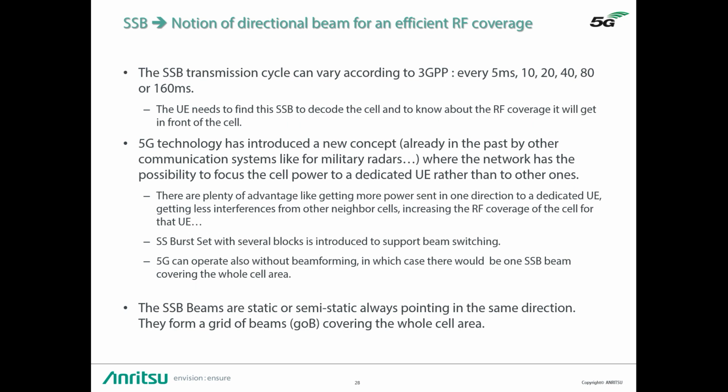The different SSBs or beams of a cell are transmitted at different times. Therefore, there is no intra-cell interference among the SSB beams, and at least the scanning receivers should be able to detect even extremely weak SSB beams, even in the presence of a dominant, strong beam from the same cell.